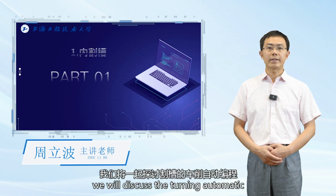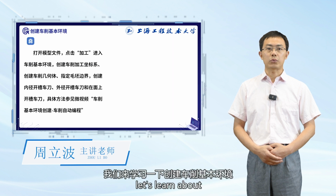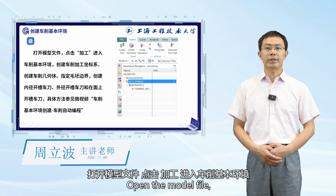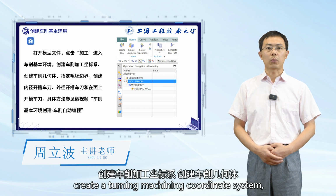Today, we will discuss the turning automatic programming of grooving. First, let's learn about creating the basic turning environment. Open the model file. Click Machining to enter the basic turning environment. Create a turning machining coordinate system.